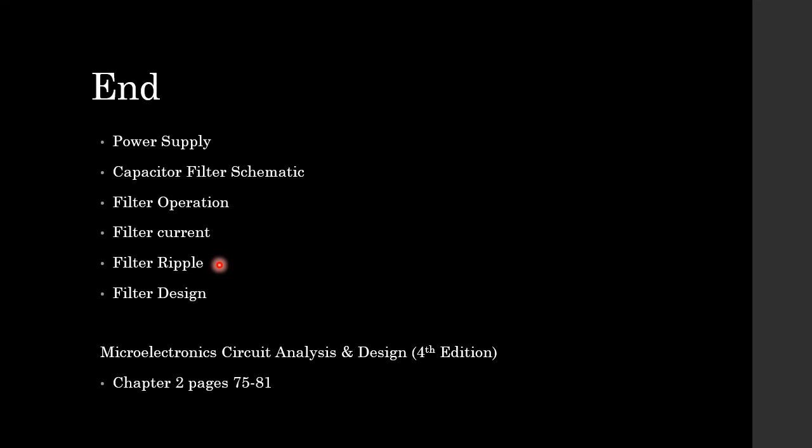This is quite a hectic derivation that I've asked you to look at in your own time. Please, students, take a look at that. And then finally, students, I took you through how to design your filter circuit from selecting or expressing your ripple to selecting or calculating your capacitor value, and then making sure that your capacitor voltage is not exceeded by the output voltage of your circuit.